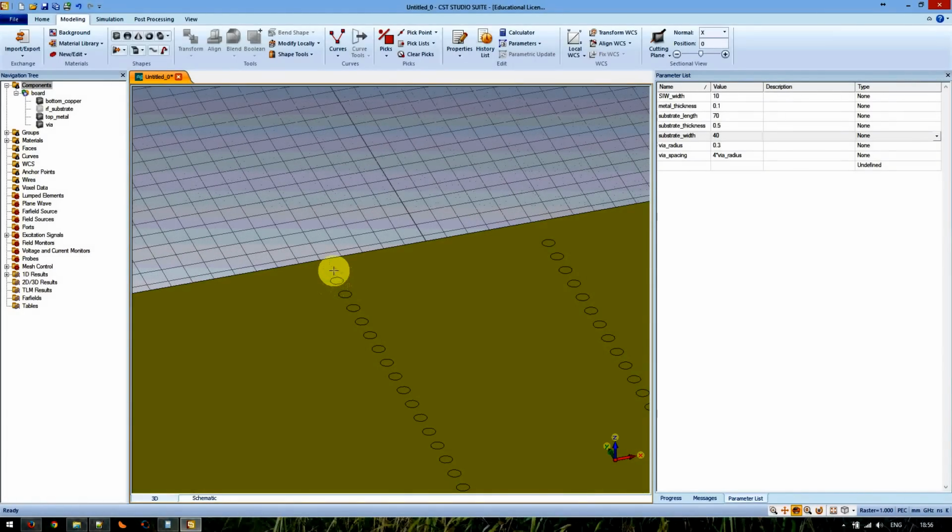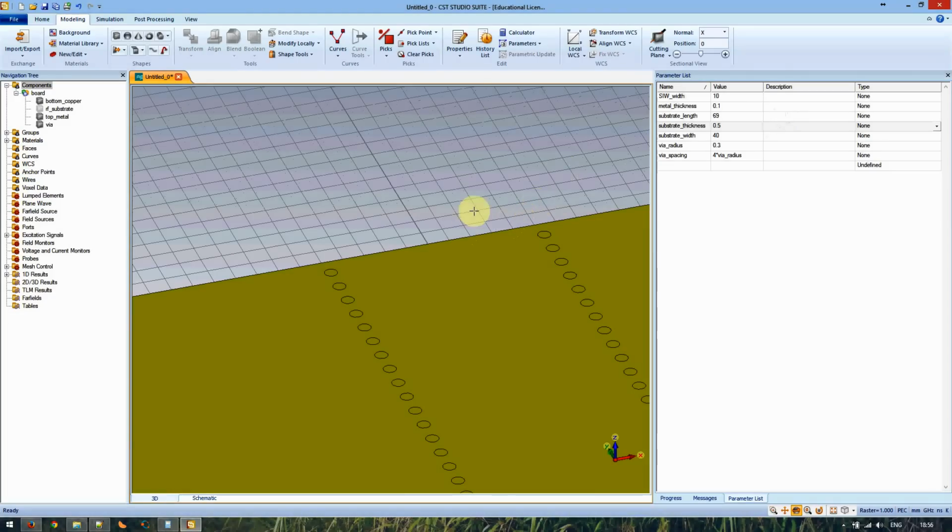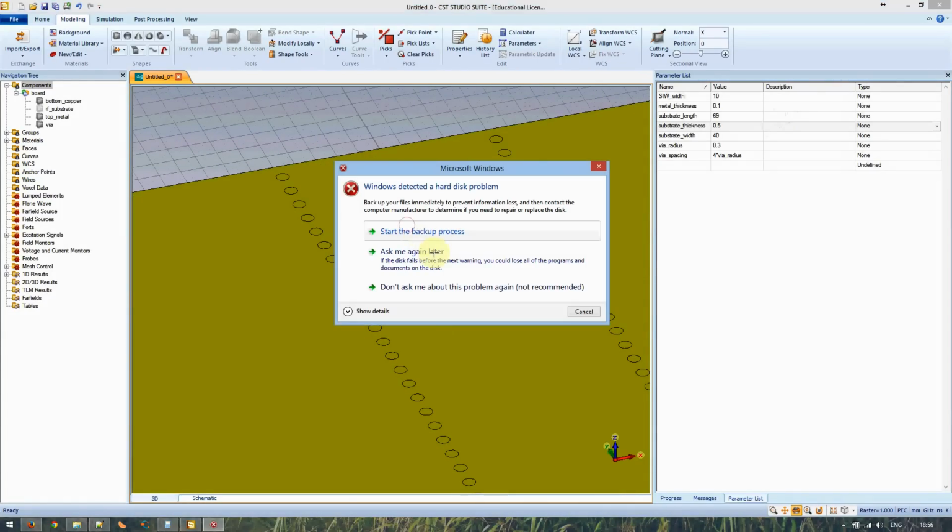Because this is an integer thing, sometimes the spacing between the board edge and the last wire is a little bit unsatisfying. So what I generally do is sort of shorten by maybe a millimeter, 69, just to make things look a little bit even. If you have a more serious design, you want to be a little bit more rigorous than this, then you can.